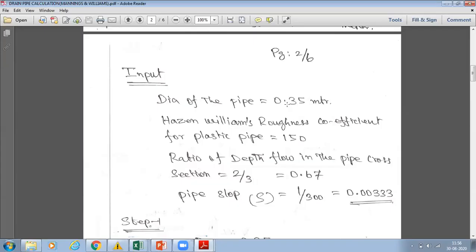With the flow and slope, everything, this formula you have to put into the Excel sheet. You have to get all the pipe sizes, the flow rate, and how much the slope is, and put everything into the Excel sheet. Then you can apply that data into your layout. So you can't get the pipe size directly from the flow rate.